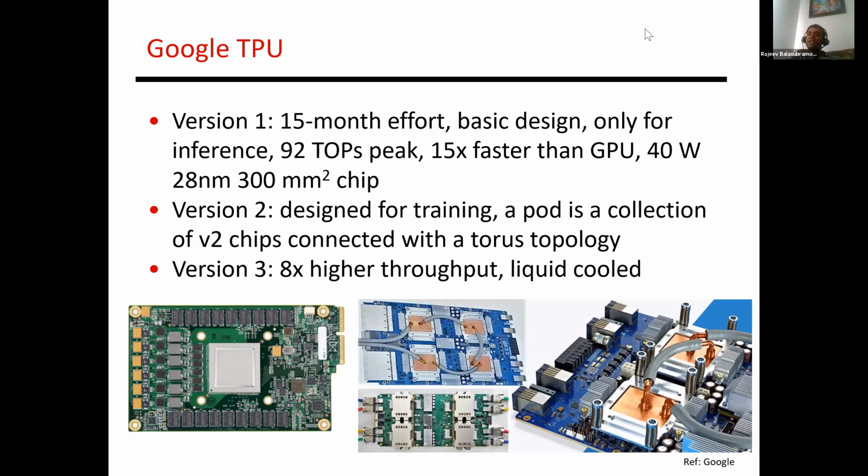And if you're in a Google data center servicing queries, you also care about what is called tail latency, right? That is, how long did the slowest responses take? And you want to bring that down as well, right? And the GPUs, because they have these extra microarchitectural features that cause variance in latencies, they wanted to go with something that was much more deterministic, that was customized for the regular computation that you see in deep networks, right? So that was some of their motivation for doing this.